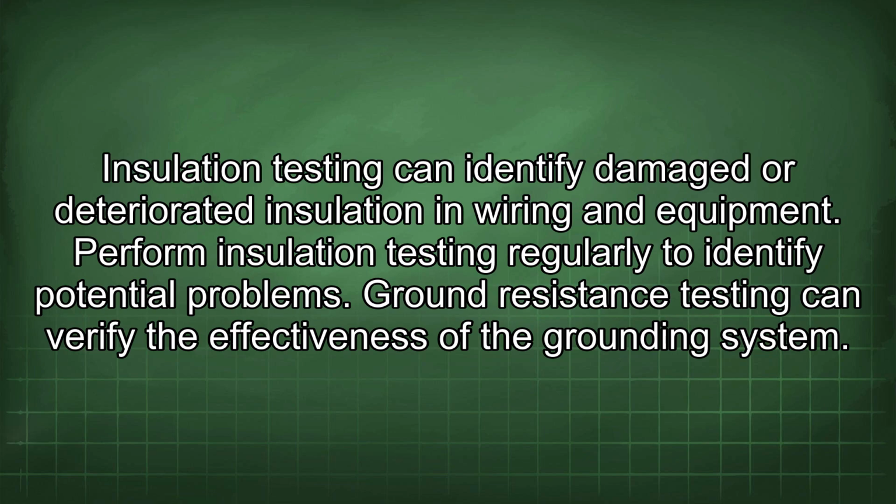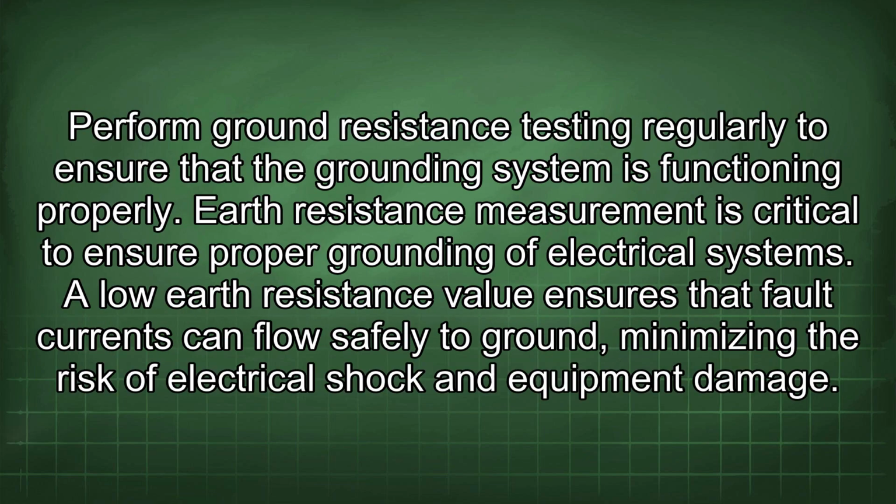Insulation testing can identify damaged or deteriorated insulation in wiring and equipment. Perform insulation testing regularly to identify potential problems. Ground resistance testing can verify the effectiveness of the grounding system. Perform ground resistance testing regularly to ensure that the grounding system is functioning properly.